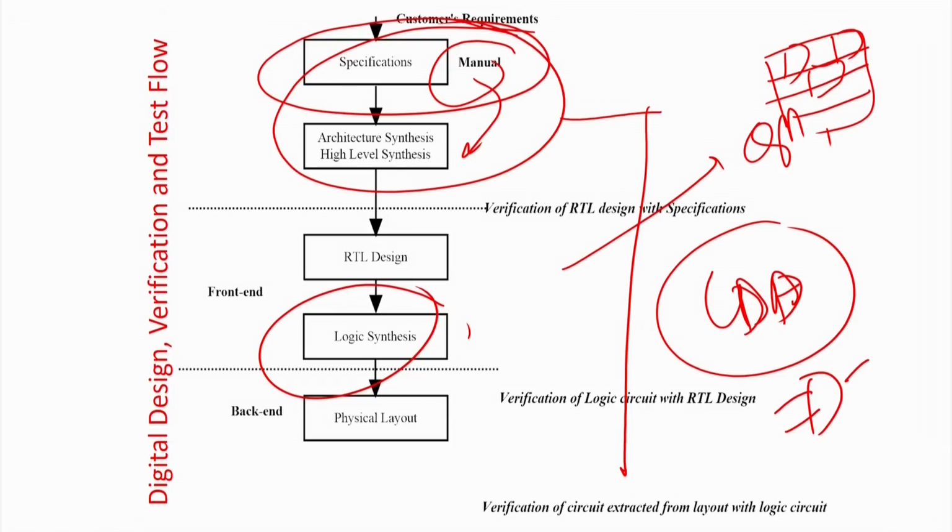But now what is the optimization here? If I get a very big die, I can put a lot of gates and a lot of vacant spaces will be there. It will be very easy to place and route it. But this is a very unoptimized design. If you want to bring it closer, then I have a very small circuit and I have to put all the gates. But if you make it too small, then you may not be able to put all the gates, and routing may not be feasible. So you should have a reasonable die size so that I can put the gates reasonably, I do not waste too much space, and still I can complete the circuit.